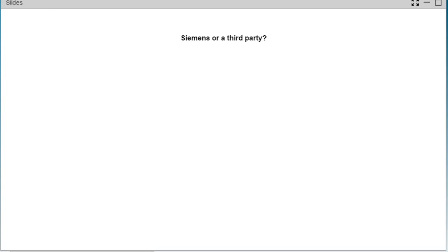And the next question is, how would you make drawings from your multi-CAD assembly? Okay, so when we're working in a multi-CAD, because of the JT data, when I take a CAD item and put it into Teamcenter, Teamcenter automatically creates a JT file of that. And that's how we're able to visualize that information very quickly through Teamcenter and even through Active Workspace.